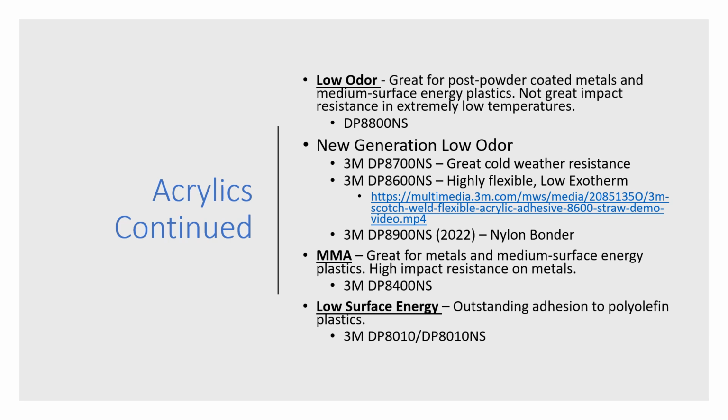And then you have lastly your low surface energy acrylic adhesive. This is going to be your DP 8010. This product is made to bond to super low surface energy materials like polyethylene, polypropylene, TPEs and TPOs, thermoplastic elastomers, thermoplastic olefins. That's what TPO and TPE stand for.